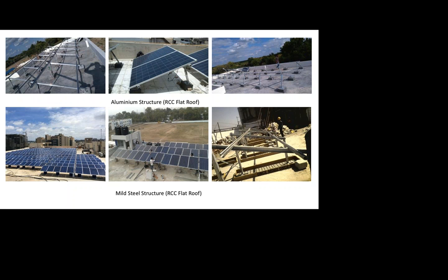But you mentioned very nicely that in case we have a short duration project, then we should go with the Hilti solution, because with Hilti you can complete the project in a very short duration of time. Hilti is available ex stock and can be done very fast, whereas in situ casting will increase the time. On a thumb rule basis, as per Indian standards, you have to do 7 days of curing before loading any foundation. In those 7 days, you can commission a project and go away from site if you're going with Hilti.